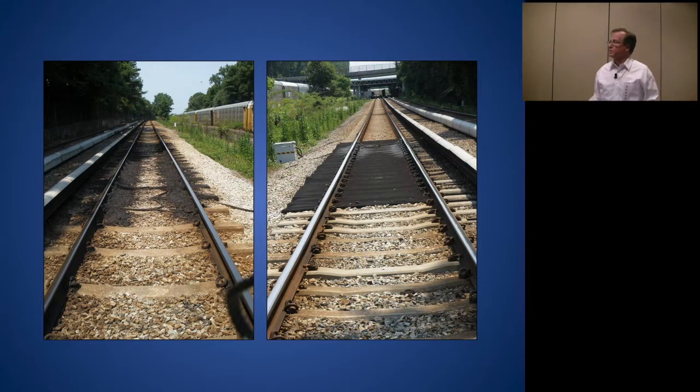Here's a problem we fixed. This is what they call a rail lubricator. It's to make the rails not make noise. Mostly, it's rail squeal. It pumps grease out onto the wheels. Well, you can see it kind of builds up. And grease in itself is not really all that conductive, unless they use a lot of additives in the grease, and then it can be more conductive.